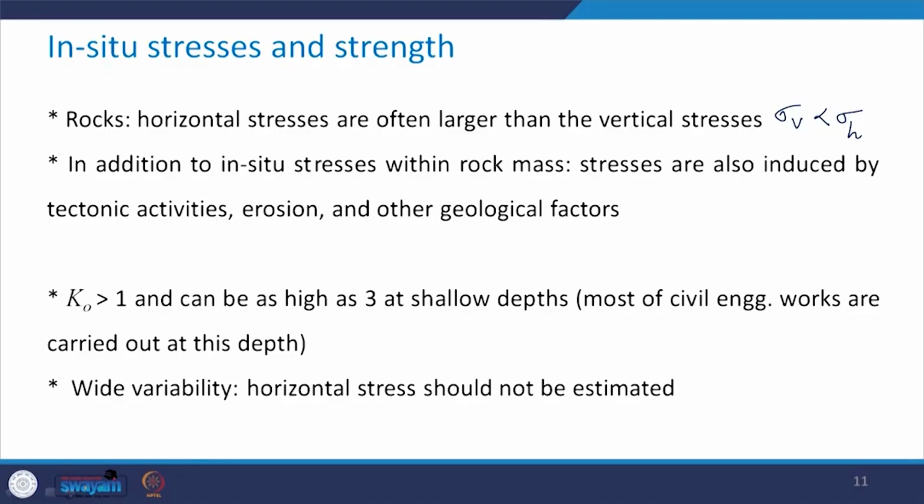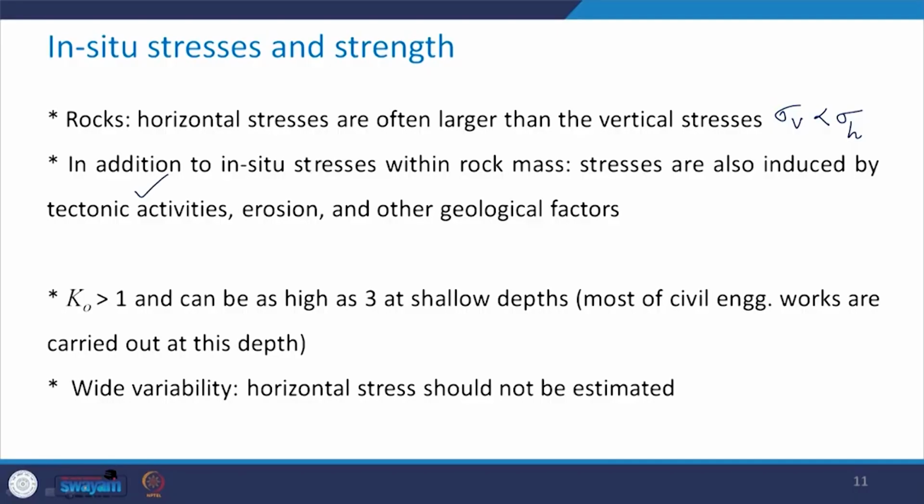That is, generally your sigma V will be less than sigma H. In addition to in situ stresses within the rock mass, stresses are also induced by various tectonic activities, erosion and other geological factors, and these contribute towards sigma H being more than sigma V in case of rocks.